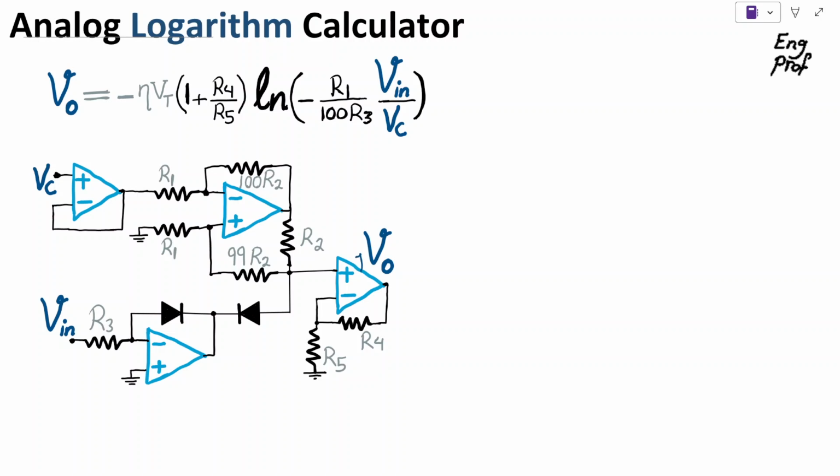First thing is to make the assumption that the supply voltages of all the op-amps are properly connected, positive and negative supply, and the op-amps are all in the linear region of operation with dominant negative feedback. So virtual short is valid for all the op-amps, which means the voltage at the positive input terminal is equal to the voltage at the negative input terminal. If on op-amp 1 here we have 0 on the positive input terminal, then for the negative input terminal, we have 0 as well.